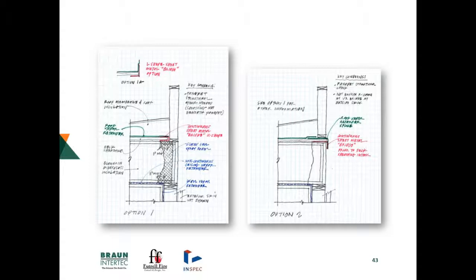The second one on the right, we started looking at maybe creating a marriage at the very outside edge by looping over the plywood deck that's installed a piece of self-adhered vapor retarder connecting to a metal continuous bridge. We did a WUFI model through that which showed some moisture accumulation out on the outer edge because there wasn't much R-value on the exterior wall at that location. So we ruled that out.